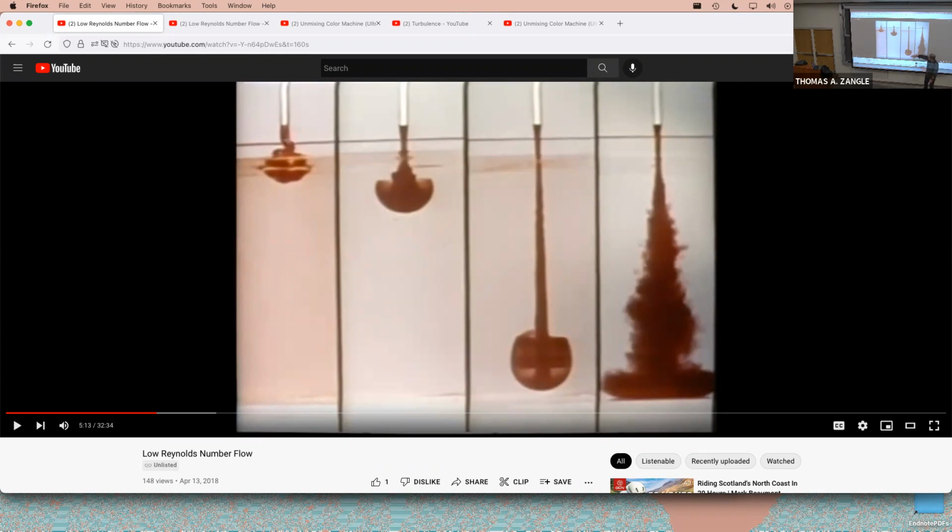And note that here, this is Reynolds number 200. This is still laminar, right? So all of these are laminar. But in the second demonstration, we have ultra laminar flow. We would call it creeping flow or Stokes flow, which is what this is over here. So we're at Reynolds number much less than 1. It's laminar, so it shares some characteristics of ordinary laminar flow, but there are some other strange properties that we're going to see when the flow gets slowed down.